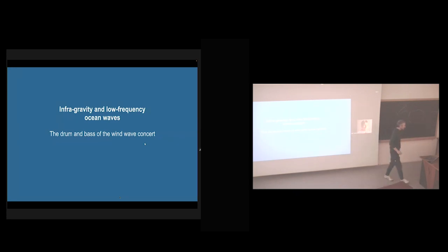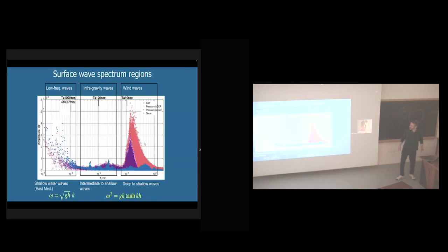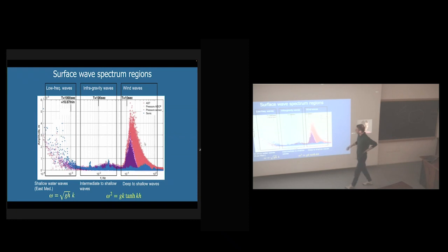Let's call them the low frequency oscillations in general. If I look at a spectrum, these are measurements of acoustic surface tracking from an ADCP, a pressure cell outside of Haifa port, and this measurement is with a sonic within Haifa port, on one of the piers. If we look at this area, that's the area we are used to as the surface waves. We see that the pressure is attenuating here, and we see a nice spectrum, which normally looks like a JONSWAP spectrum.